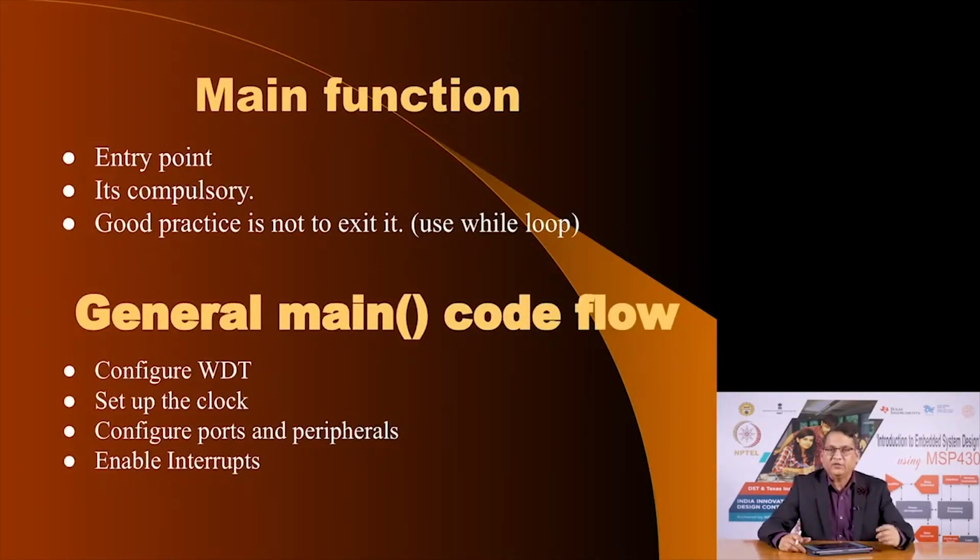At the very minimum, it has a main loop, right. That main loop indicates the entry point into the microcontroller or the microprocessor. It is compulsory and it will do a bunch of things as reflected by the code that you write. But once all those commands, all those instructions are executed, where does the main loop take you? Well, actually it does not go anywhere.